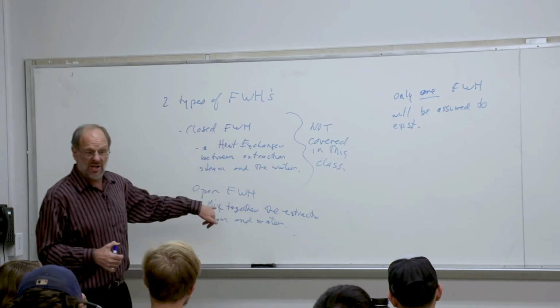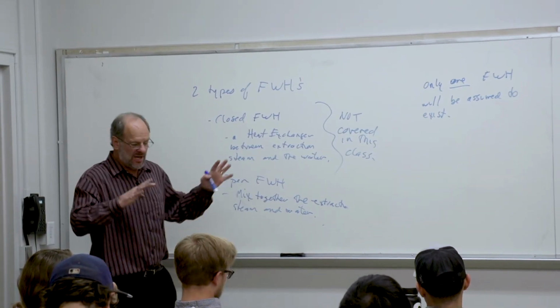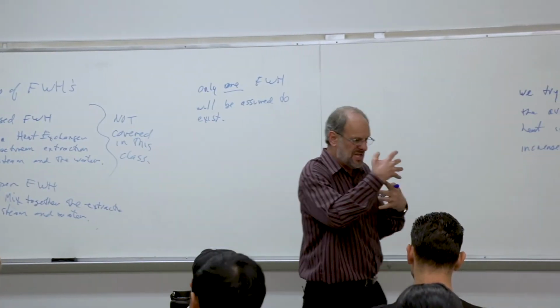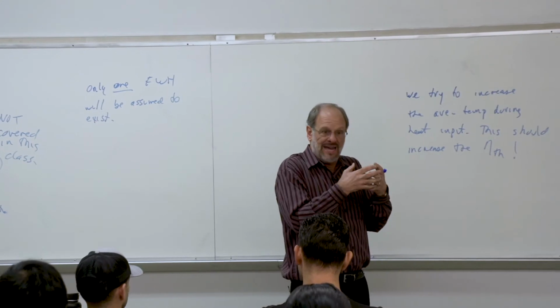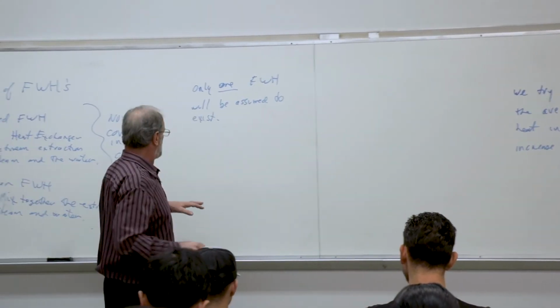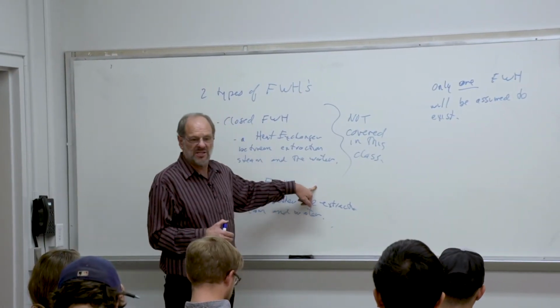So the open feed water heater will actually take care of that for you. Yes, it is a heat exchanger, but it's a mixing process, and through the turbulent mixing of steam and liquid water, air that's actually dissolved in the water will come out of solution. So you're always going to have one open feed water heater, and often it's just called a deaerator.